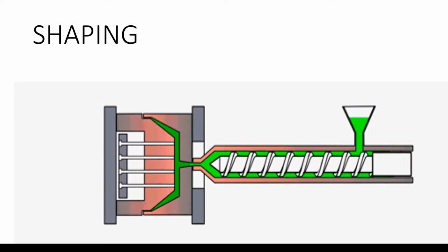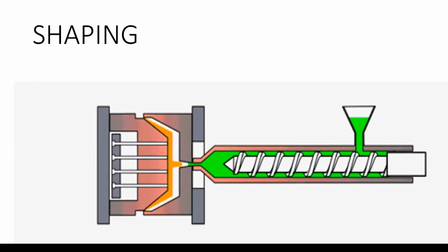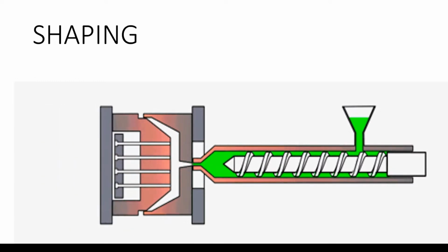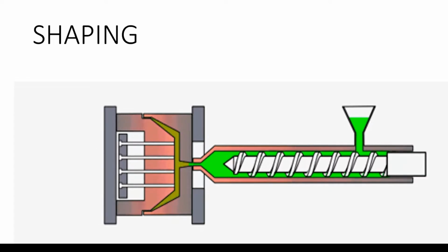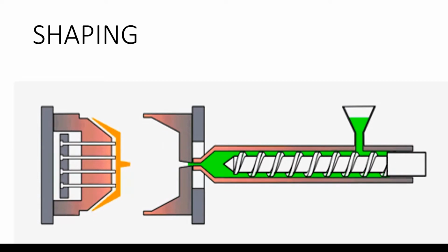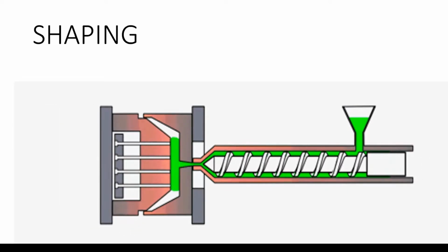The three primary methods of molding rubber are compression molding, yan baka lumabas sa exam to, which is used in making tires among other products, transfer molding, and injection molding. Vulcanization of the rubber occurs during the molding process rather than as a separate step. And the final step is, next slide,